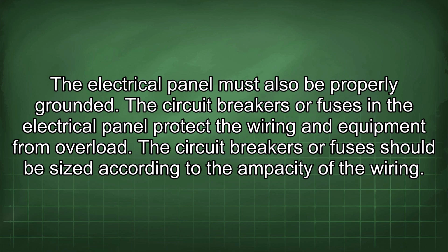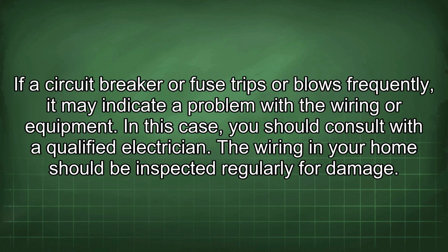The circuit breakers or fuses in the electrical panel protect the wiring and equipment from overload. The circuit breakers or fuses should be sized according to the ampacity of the wiring. If a circuit breaker or fuse trips or blows frequently, it may indicate a problem with the wiring or equipment. In this case, you should consult with a qualified electrician.